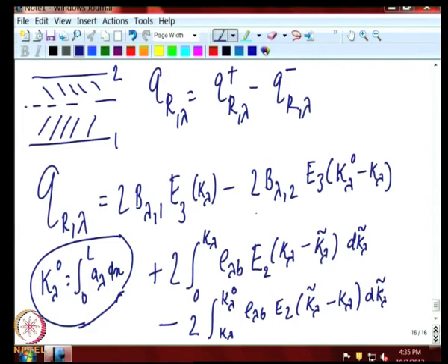That is upward flux. Then the downward flux is the radiation leaving the top surface and the distance travelled now is counted, because everything is counted. This is x going upwards, this is 0, this is kappa lambda 0.